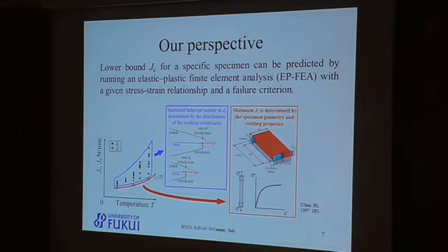We first thought to re-examine Chen et al.'s opinion that it is necessary to distinguish the concept of the minimum fracture toughness or the lower boundary value of toughness from that of the scatter band of toughness. The former is a definite parameter determined by the specimen geometry and yielding properties, and the latter is a statistical behavior determined by the distribution of the weakest constituent.